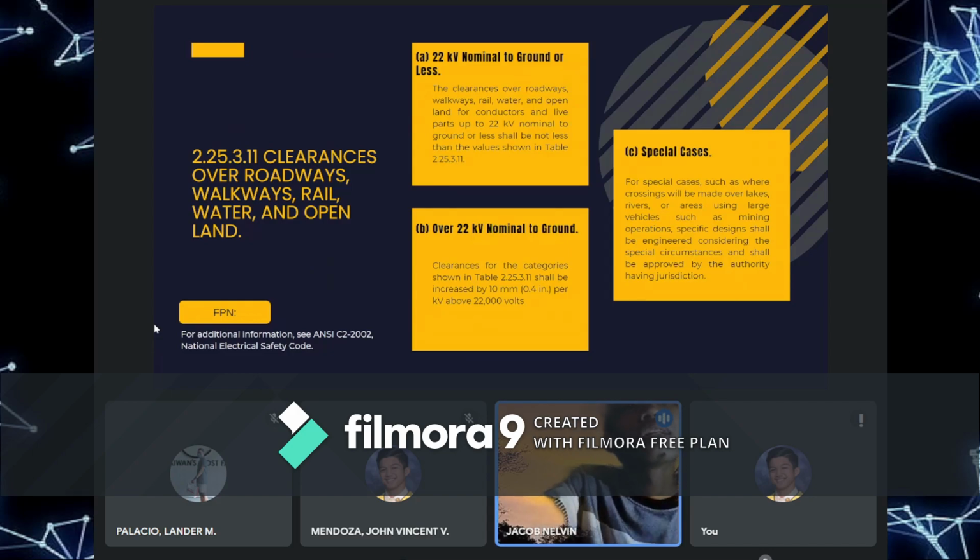Sabi, the clearances over roadways, walkways, rail, water, and open land for conductors and live parts up to 22 kilovolt nominal to ground or less shall be not less than the values shown in table 2.25.3.11. Makikita natin mamaya yung table.